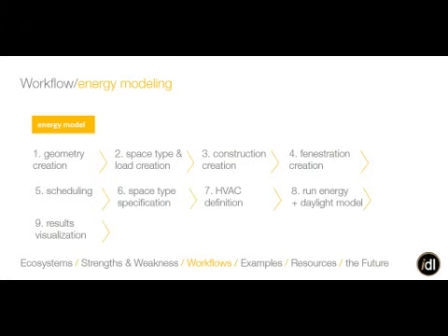And this is really a weird, tenuous dance that we go through between those three programs throughout the entire process. Generally, though, the strategy is to use OpenStudio for as much of this as possible. With each new version, you're able to get farther along the process. Beforehand, we had to stop in OpenStudio whenever we got to HVAC definition because it didn't have a good way to do modeling. But now, with the drag and drop interface, you can pretty much run through the entire thing. You really only need text mode for more advanced HVAC analysis and iterations. So that's the general strategy: OpenStudio as much as possible and text mode as little as possible.